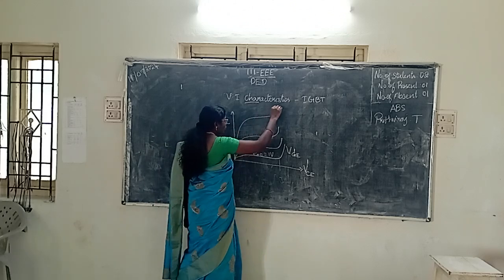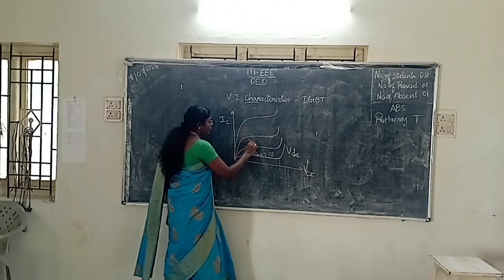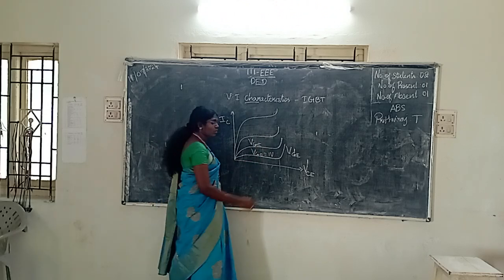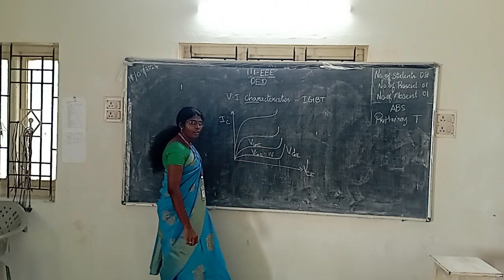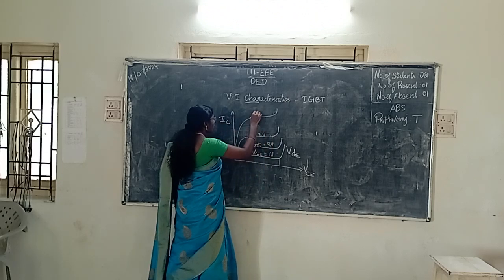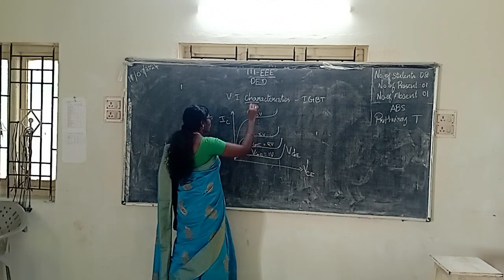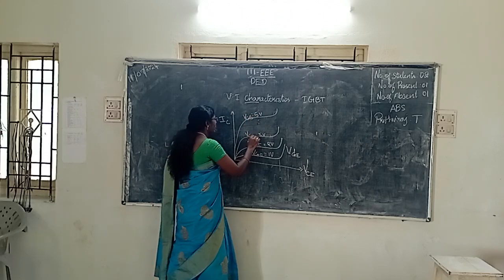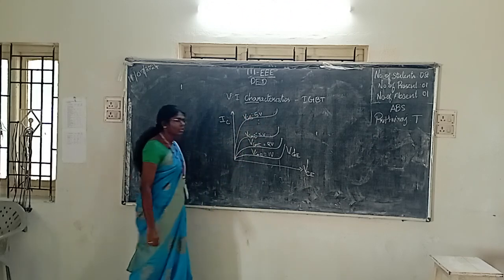VGE as 5 volt, it will increase. So we control it using the gate voltage, and it is called a voltage controlled device. VGE is 2 volt here, then 3 volt and 5 volt, and it goes on. The gate signal is going to control.